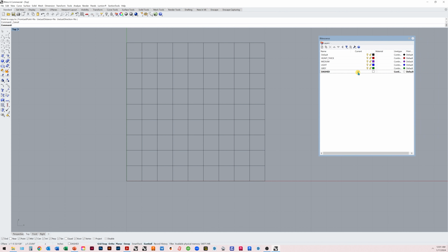Now watch what happens. See how dashed has a check next to it? Let's click on this heavy/thick line. So right now it's red. So if I go to draw a line and say maybe I want to turn my ortho off because I'm tired of drawing straight lines. If I want to draw a line that's a diagonal, now, let's try it again. Left click, right click. Now I have a red line. And then let's try if I do medium. Let's just make a quick pattern here. So I'm right clicking to repeat the last command.